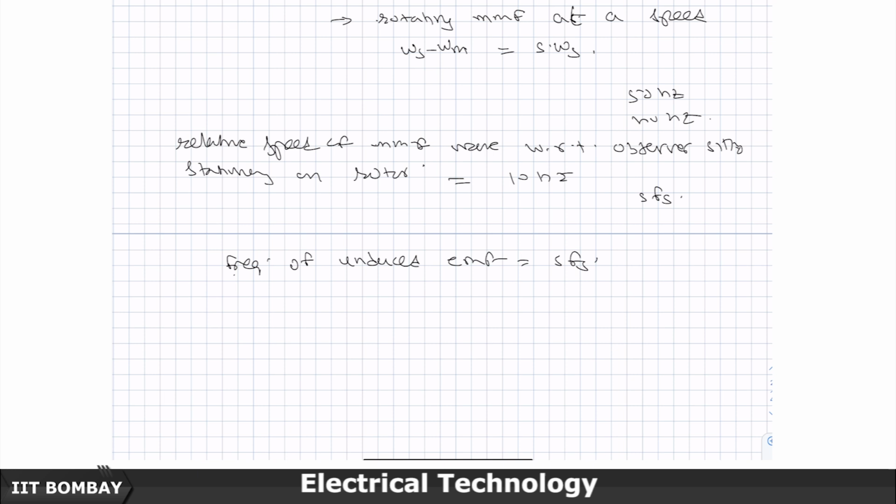But we have discussed how the mechanics of generating the sinusoidal voltage is exactly the same as what we have discussed in the elementary synchronous machine. Think of a stationary winding, actually, I am now describing it to you only. Think of it as a stationary winding and an MMF which is cutting across at a speed of omega s.